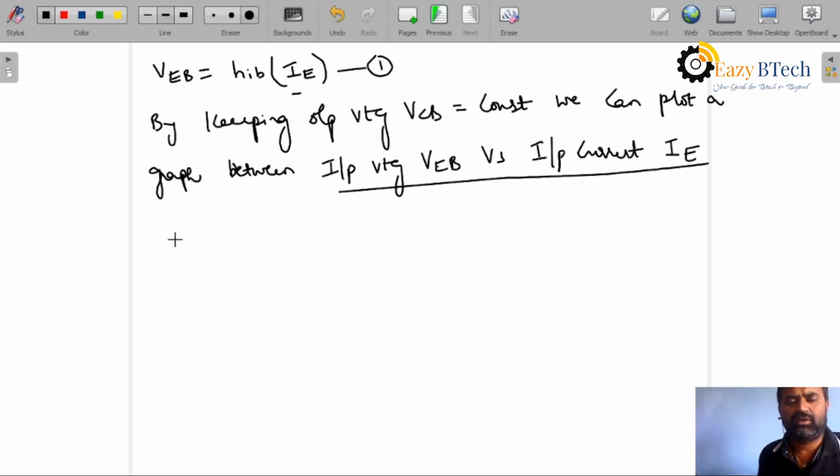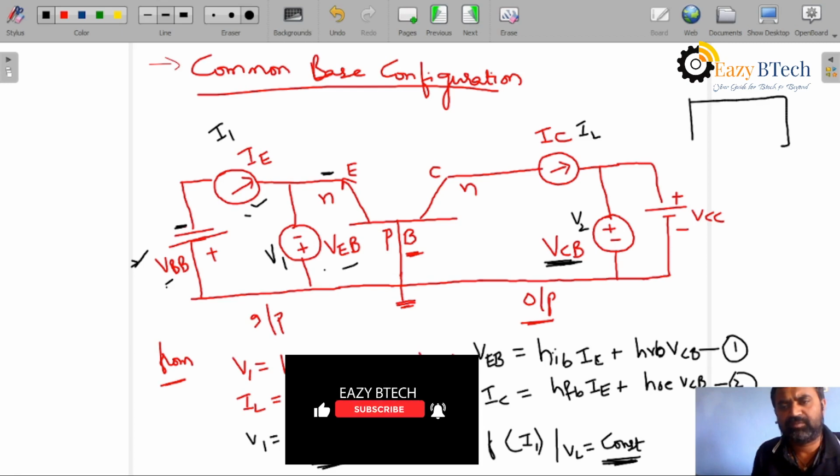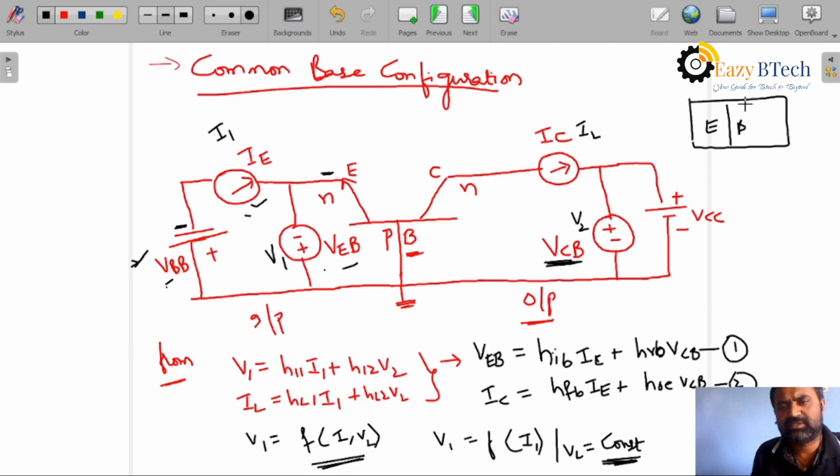Remember this point. Now if you see the diagram here, you are giving negative connected to the n-type material. It is a forward bias. It is the emitter base junction. It is emitter, base, collector. Now here, when this JE junction is operated in forward bias, the current across the junction is like a PN junction diode. Okay, students.